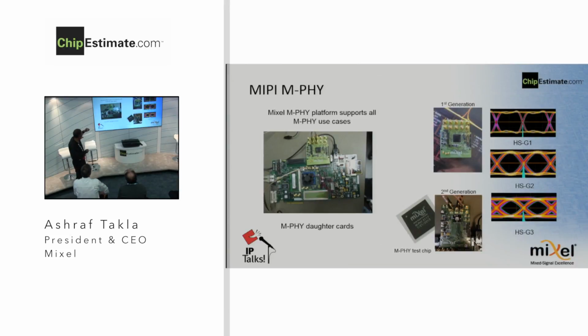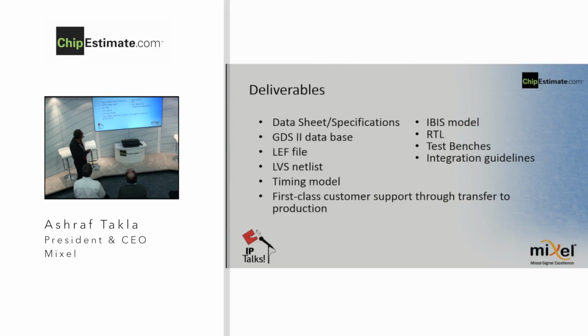We have had the MIPI silicon proven for many years now. Again, we have a platform that supports that, and this just shows the test chips, the different boards that we have built over the years, and the performance. Yeah. We deliver a full list of deliverables. Of course, GDS, the specifications, design guidelines, integration guidelines, LEF, the timing models, IBIS, RTL, test benches, and I think most important is outstanding customer support to production.